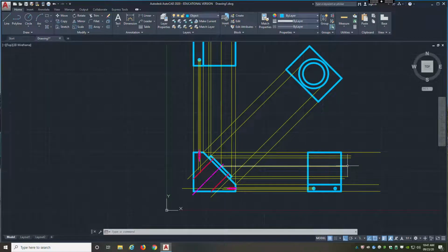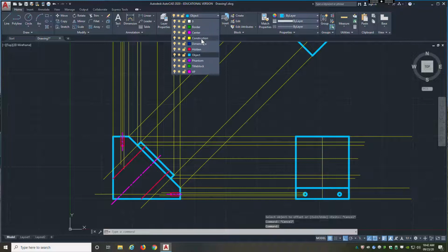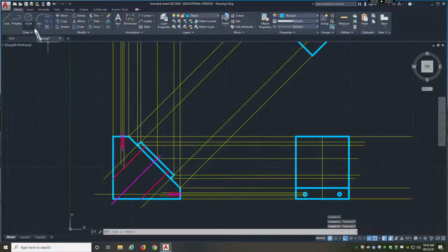So next is the ellipse, right? Because we have to draw an ellipse since it's not a perfect circle. I'm going to offset 2.125. Did that not take? Let me try it one more time. Offset 2.125, hit enter, and I'm going to offset this left just so that I have a nice center point. And what I'll do is I'll quickly convert that into a construction line. So I've got an intersection.